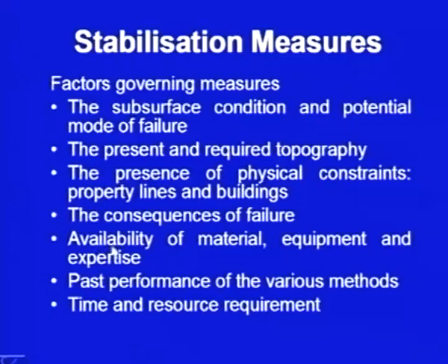Then the availability of the material, the availability of the equipment, and also availability of the expertise is very important. And also we have to see in that particular area what the past performance of various methods is, because stabilization measures are a site-specific solution, not a standard solution that you can give to every place.